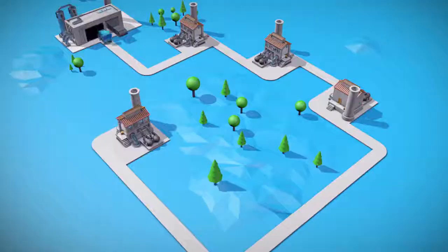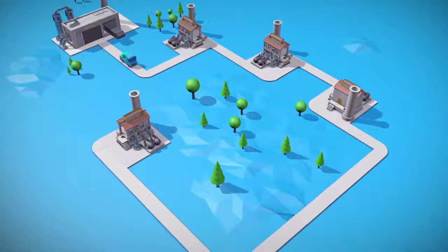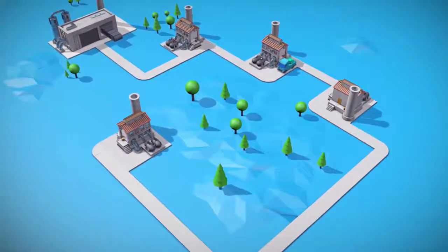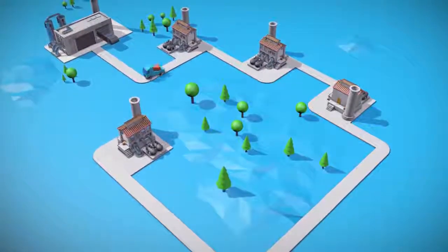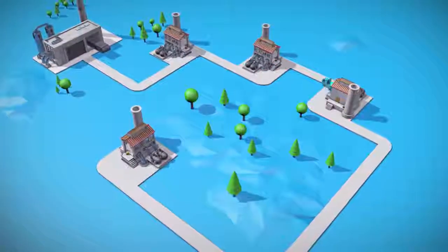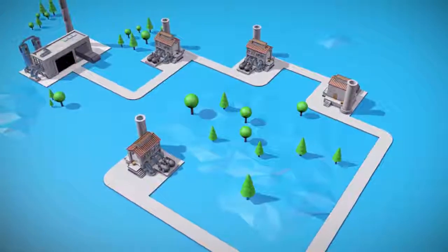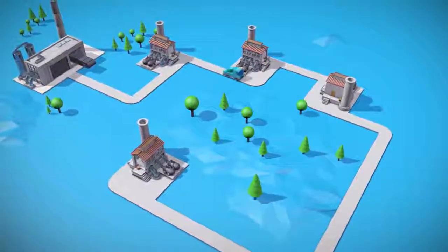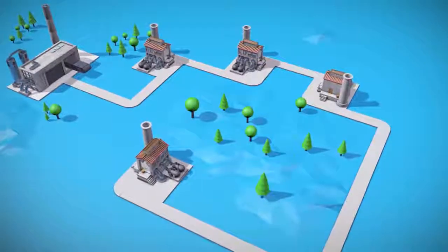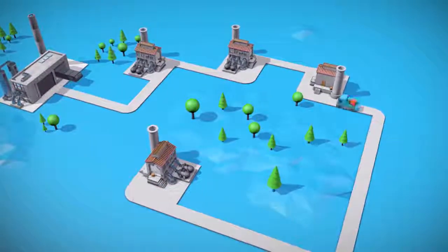Let's take a look at the OT level in the Profibus fieldbus system. High-performance infrastructure components like switches are not required yet in this context, because master and slaves only communicate sequentially according to the question-answer principle. Compared to road traffic, this would mean that only one vehicle can drive in one direction at a time between the production plant and the supplier.